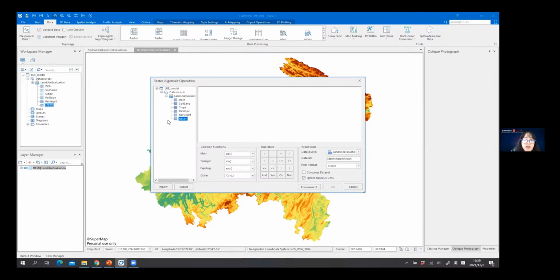We can see on the left is a list of data stored in our data source. By double-clicking on it, we can add it as a variable in our expression. In this case, the evaluation of slope is the major factor for the evaluation, and the reclassified evaluations on height and percentage of set in soil are actually how the evaluation result of slope will be degraded.